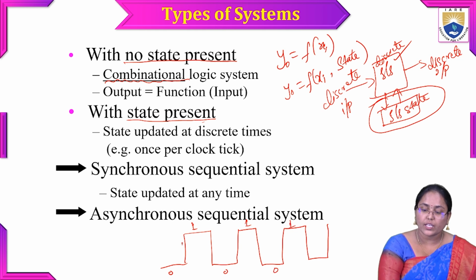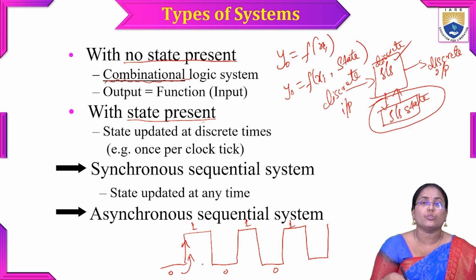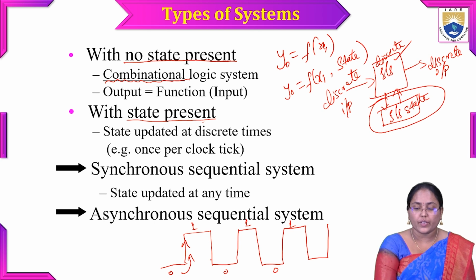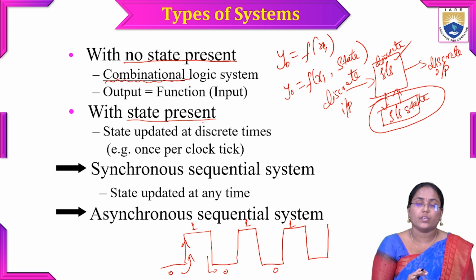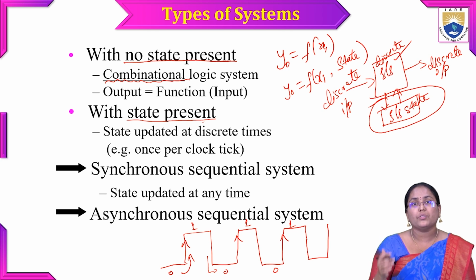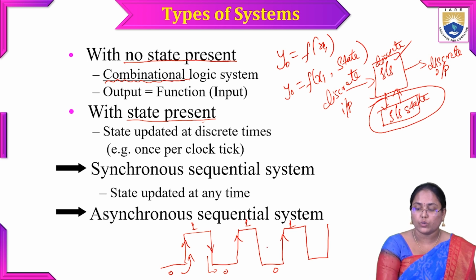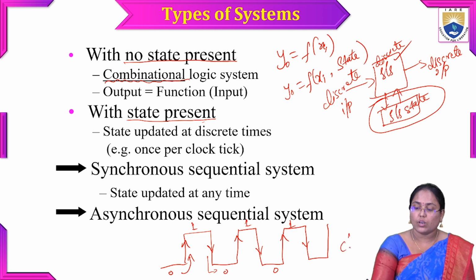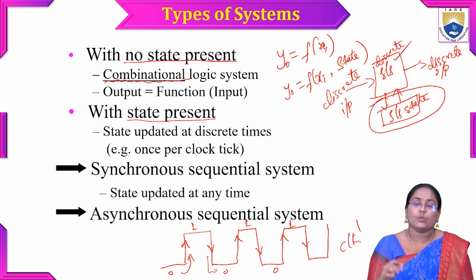Whenever there is a clock tick, that is, whenever there is a transition from 0 to 1, I'll be getting an output. If I am considering clock ticks, then for every clock tick we should get the output. Or on the contrary, if we get the output whenever the clock decreases from 1 to 0, then we need to consider only those transitions. That is a clock negative tick, clock tick hash, which we'll write like this in the code actually.